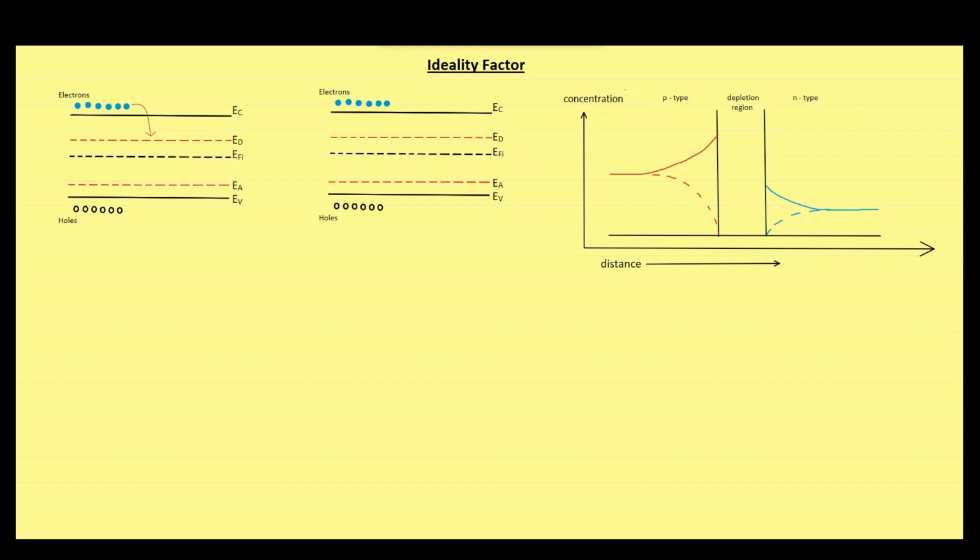And the second case is these electrons will interact with holes such that an electron-hole pair recombines, which ultimately decreases the concentration of both holes and electrons. The first possibility is not possible because we have taken depletion approximation to be valid, which means that all the dopant atoms, whether they are acceptor or donor, are all ionized. And the second possibility is not possible because of the Shockley ideal diode approximation. The conclusion of considering these two approximations is that the probability of recombination is 0. But in practical diodes, it is obviously not true.